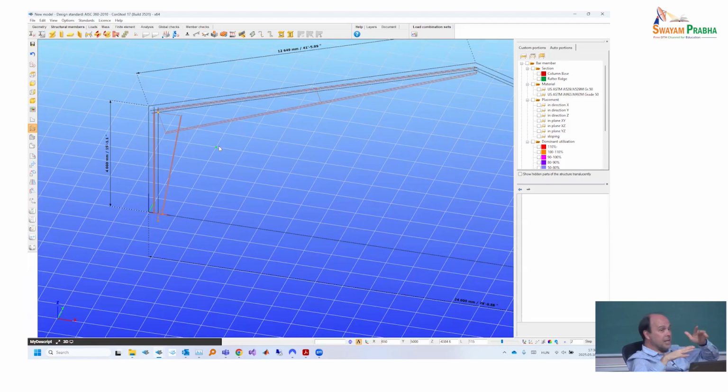But as a consequence, each purlin line can be considered as a lateral point support. And then, in addition, we will also consider that those purlins which have flange braces. A flange brace is typically an angle or any sort of profile which is connected to the inside flange of the I section, and in a diagonal direction close to 45 degrees, it connects the bottom flange of the I section to the roof purlin.